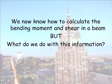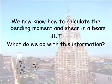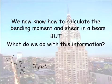calculate a stress. When we did our truss design, we calculated a force and we effectively equated it to our yield stress. So in your project, you were calculating the force from your method of joints. You're saying force divided by the area has to equal a stress, and we're going to equate that to the yield stress.